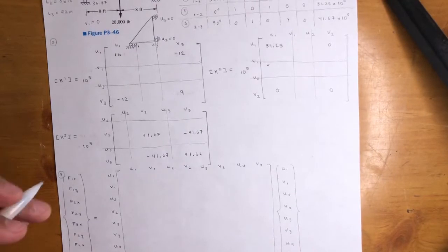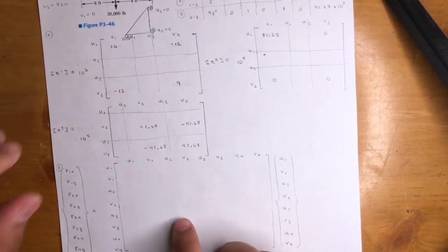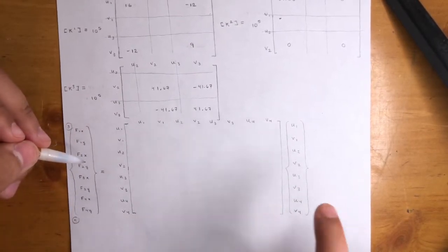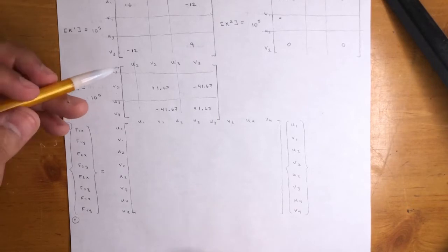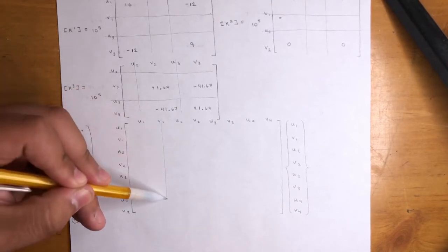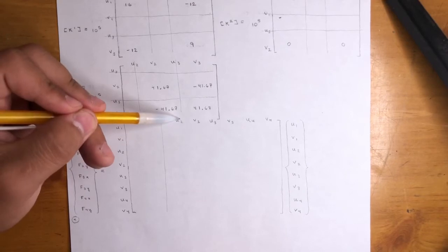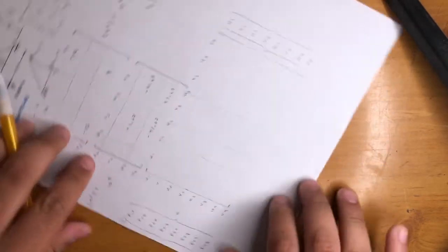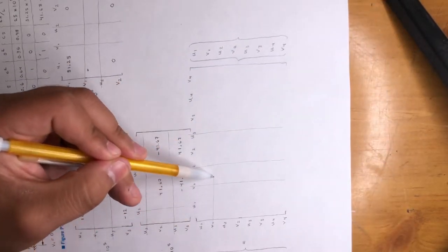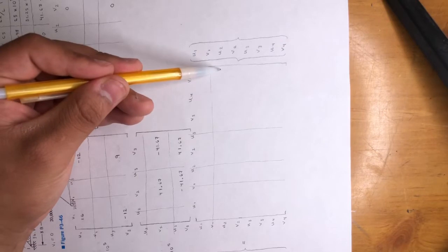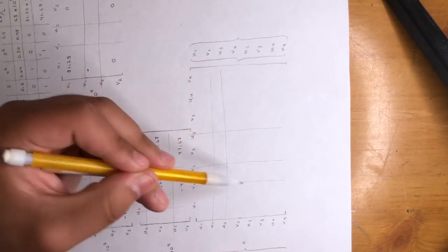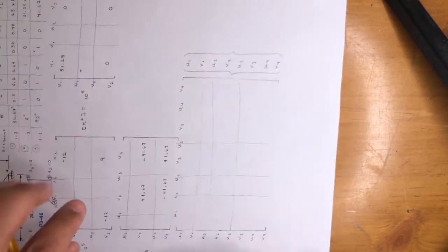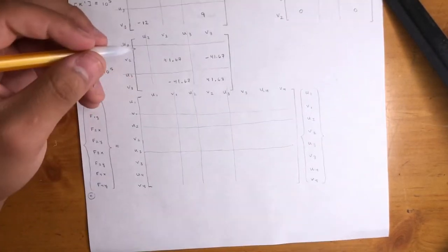Now, before we do that, we could go ahead and start doing the boundary conditions again to the global stiffness matrix. This is your global equation, right? You've got your force vector, global stiffness matrix, displacement vector. Let's go ahead and apply the boundary conditions. V1 is 0. U3 and U2 are 0. U3, there we go. And same across, right? V1, U2, and U3 are all gone. They're not the straightest lines, but they'll work for now, okay?